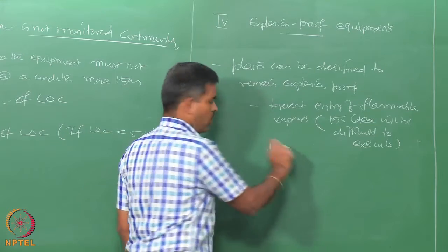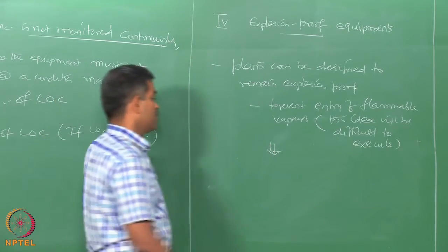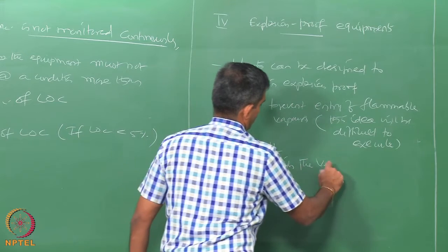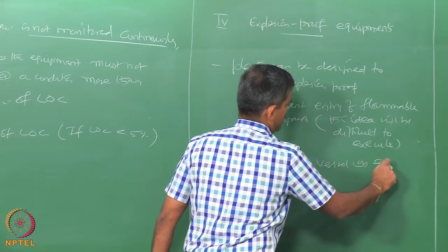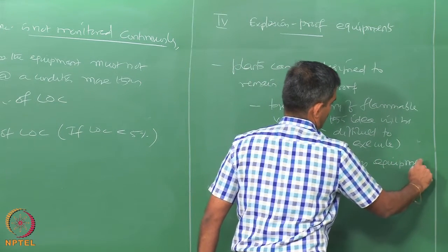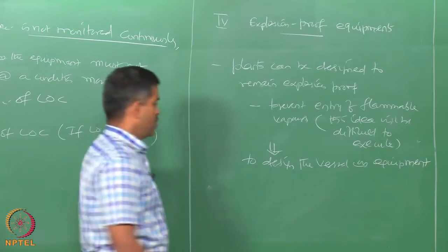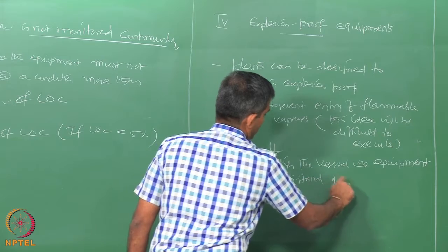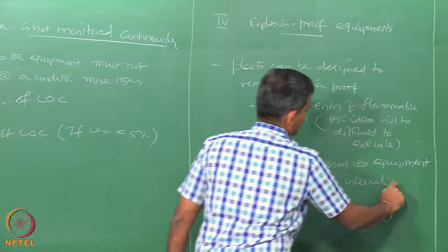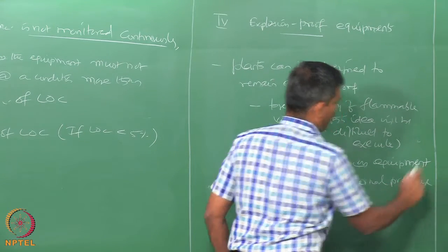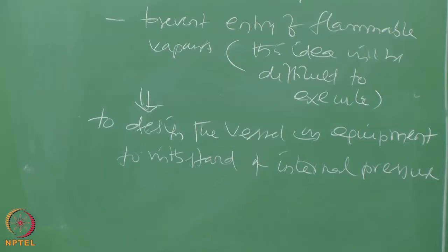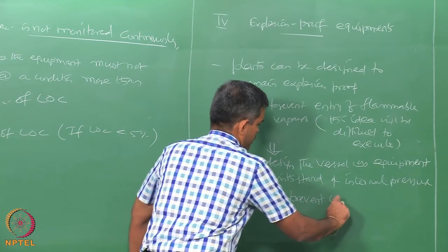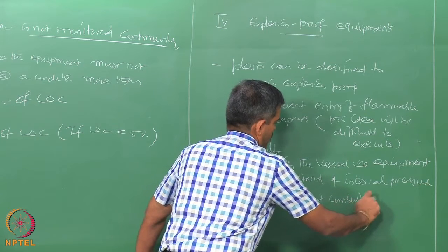hence people follow the alternative, to design the vessel or equipment to withstand high internal pressure. So, that is the common design phenomenon people generally follow to make them explosion proof, so that it can prevent combustion by design.